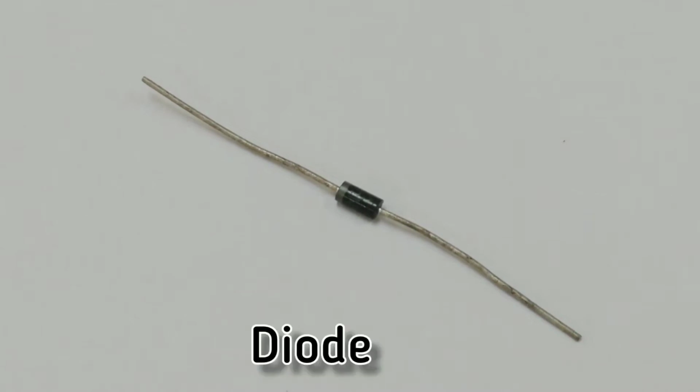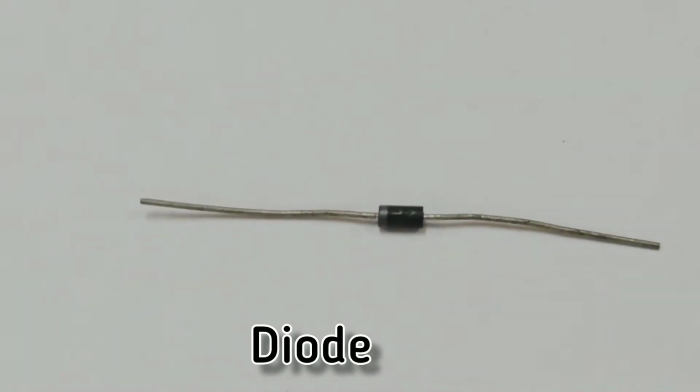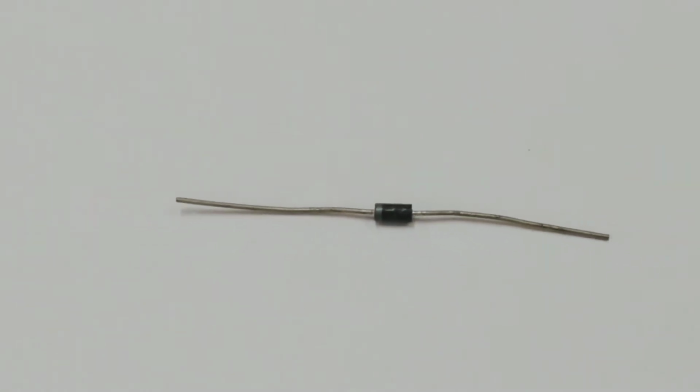This is a diode which has again two terminals, but on the diode you can see that there will be a silver line indicating the polarity of the diode. Silver line indicates negative side of the diode. It has two ends, but both the ends of the diode are in a straight line, unlike your LED.